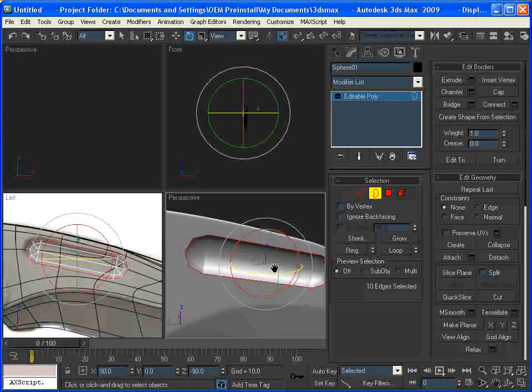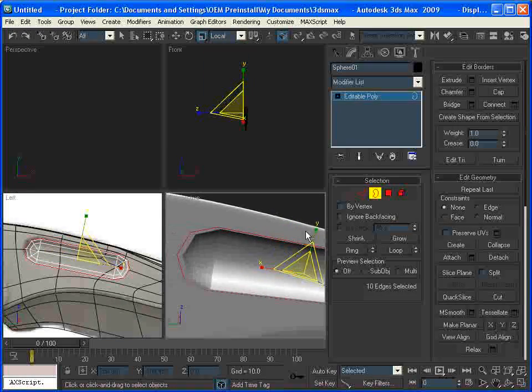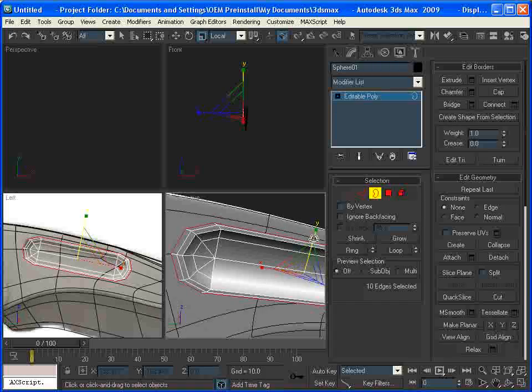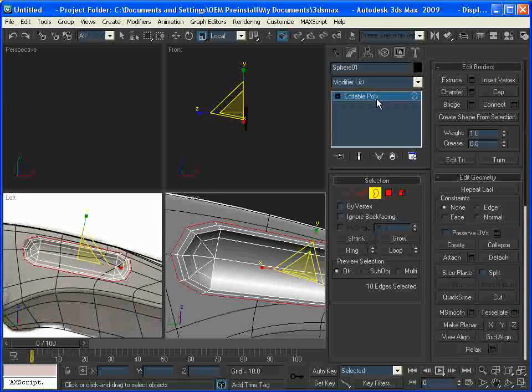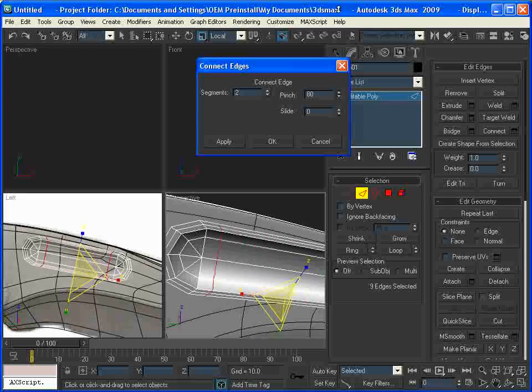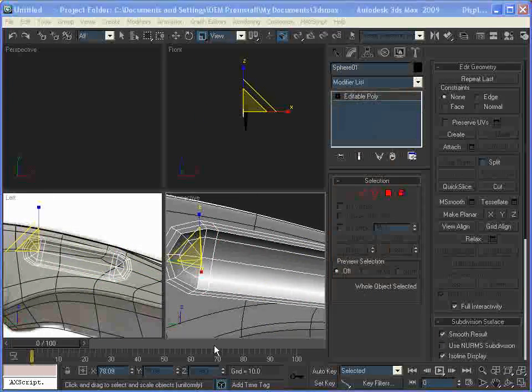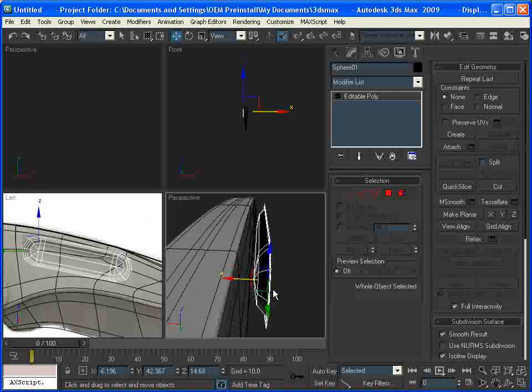And then just so we get some nice edge highlights on the side, I'm just going to extrude a few rings out of it. And to make sure it retains its shape, I'm just going to add a few supporting edges in there. Now we move it, or collapse it a bit, we move it right next to the surface we want it to float over.